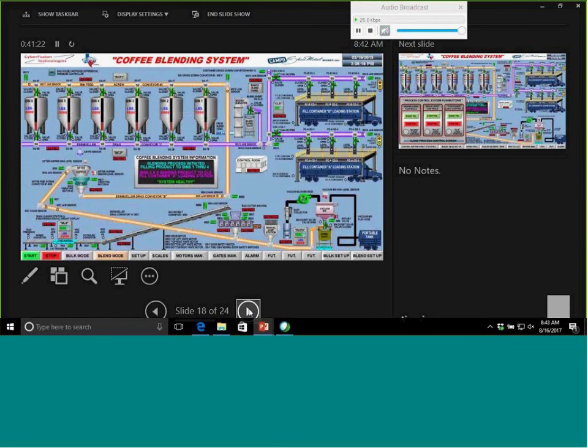Same thing, we have a manual dump station. If they want to take an existing super sack and put it into the system, they can do so from there, and then we can draw product from a portable tank or container that comes in, and utilizing vacuum, we can transfer that product into the vacuum bin and also send that product into the system. And then at that point,